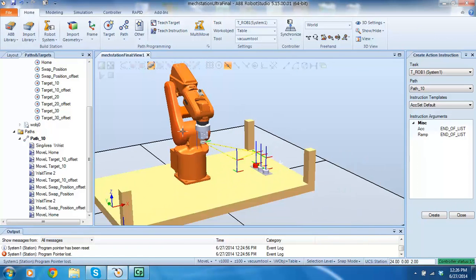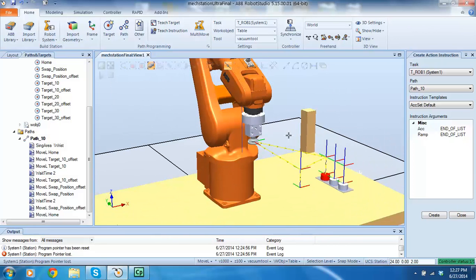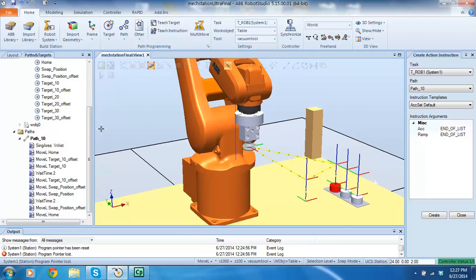And what we've done is we've wired up this vacuum chuck to a directional control valve. If we output a signal to the directional control valve, it turns on the vacuum chuck. If we turn off the signal to the directional control valve, it turns off the vacuum chuck. Now, I'm trying to figure out which output Elliot wired to. I'm pretty sure that it's actually digital output 0. 0 is what the solenoid, the directional control valve, is wired to.